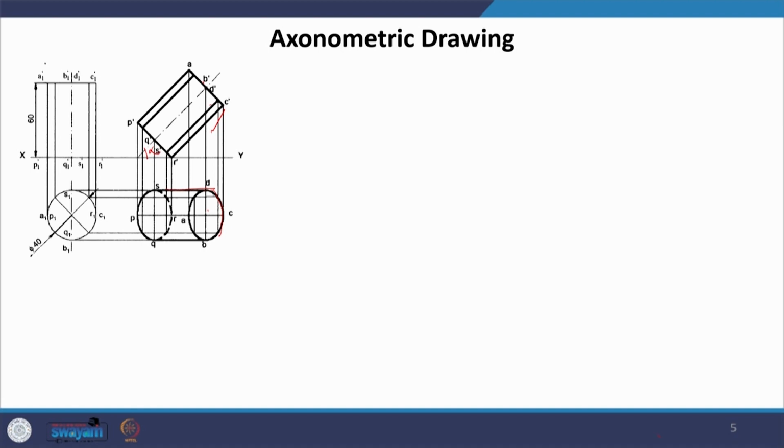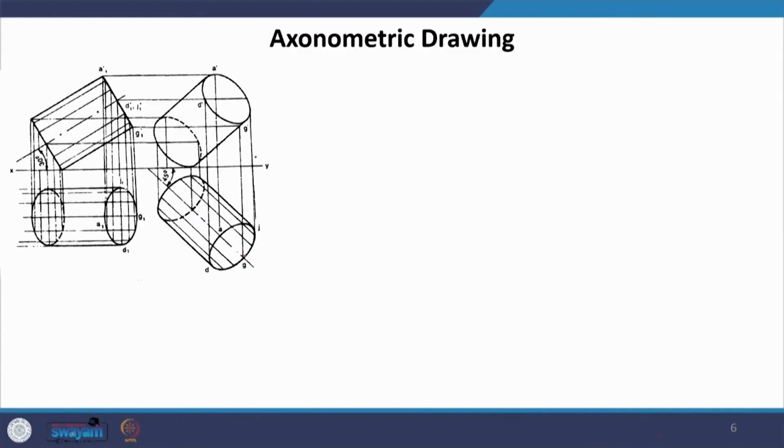I am leaving this one out for you, but I wish that you will all try this at home, and in case you face any problem, you can come back to us and we will solve the query. This one is doubly inclined. Now, here we can see how this one is going to come, where it is doubly inclined, and we are not going to draw the faces separately and the rest of the body separately. All I am going to do is draw the plan and then take the vertical projections of each of these points and arrive at the projection.